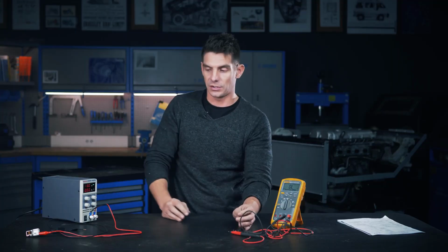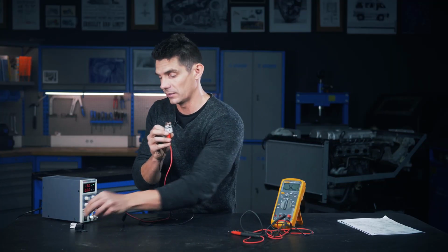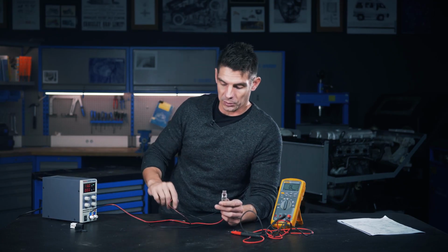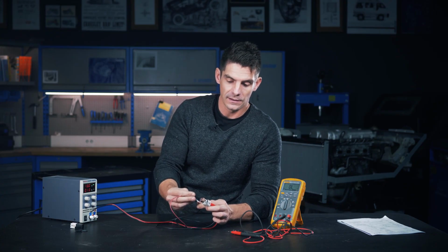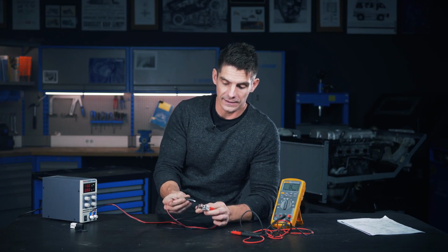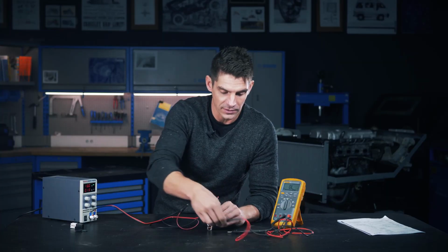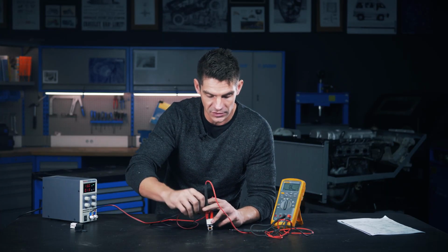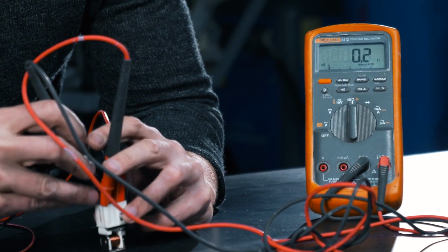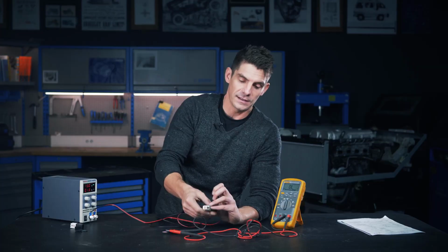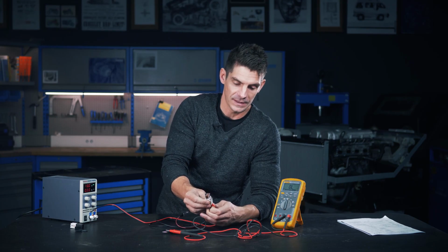The next thing you would want to do, as we've done here, in fact, let's just use this one that we're already connected to, is apply 12 volts across the coil and listen to see, does the relay click? Then you leave your 12 volts across the coil and measure for continuity across the 2 main contacts, and hopefully we hear a beep. There we have it. So we know that this relay works perfectly, even though I've butchered it.